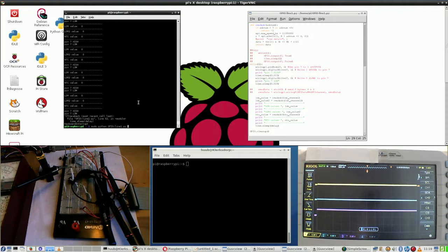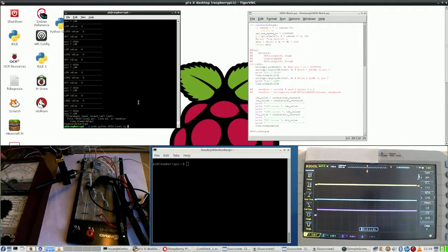And I realize that you don't see anything on the multimeter. Anyway, here is nothing. Here is nothing visible. And when I measure here, you see clearly the 3.3 volts. Now, what would I need to see on the blue wire right here, since that is directly connected to the SPI channel, channel 0 actually.